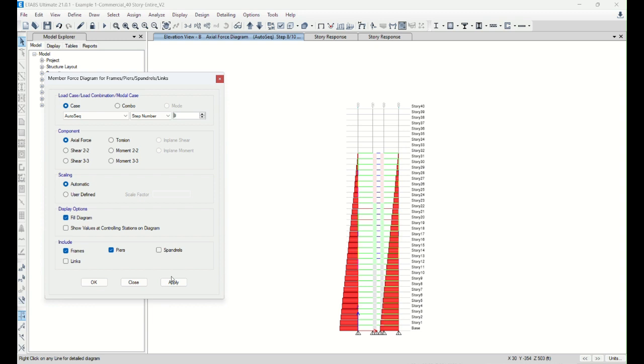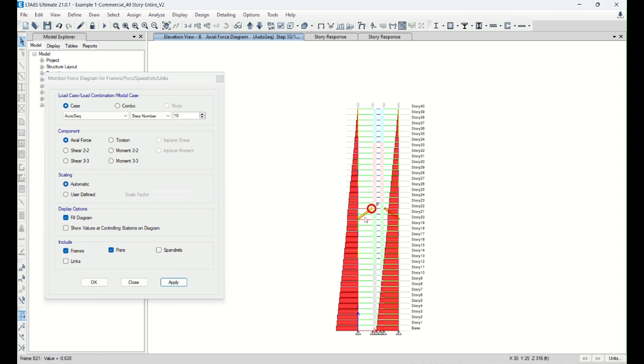So then we assume that we're not going to install this outrigger truss, or we place it, but we don't tie this outrigger bracing completely, right? Just leave it as kind of open connections. But after our construction is completed, we tie the bracing element, which means bolting, right?